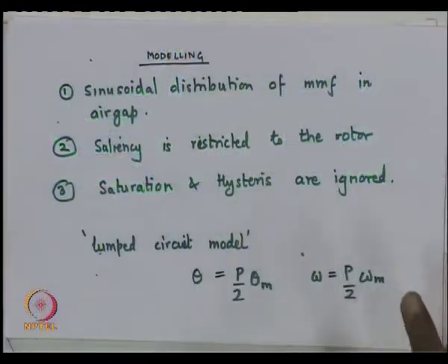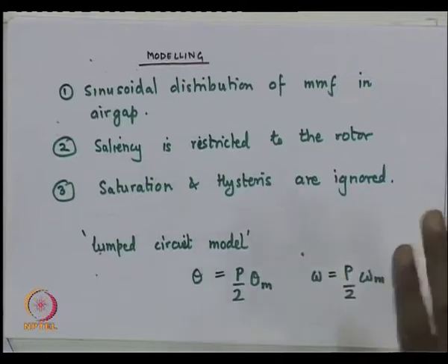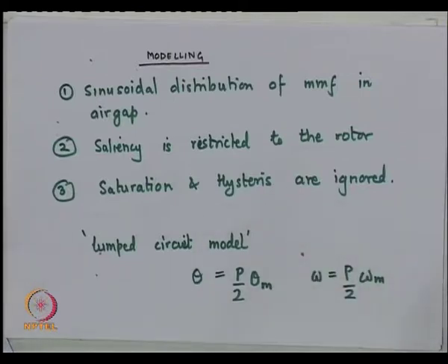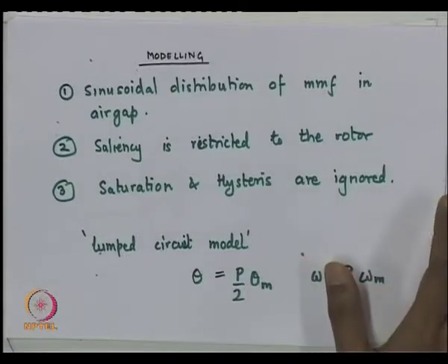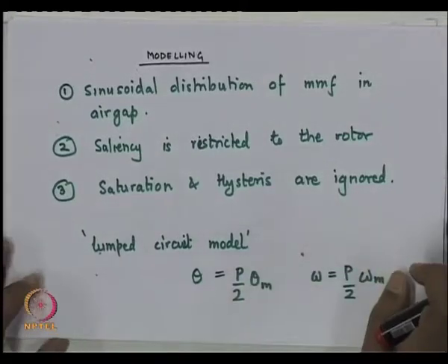In particular, we will be taking what is known as a lumped circuit model of a synchronous machine. Obviously, this kind of model will not be adequate to study phenomena which are affected by parasitics and so on. Roughly, you can say that phenomena which last more than say 1 millisecond can be studied reasonably well by this kind of model.